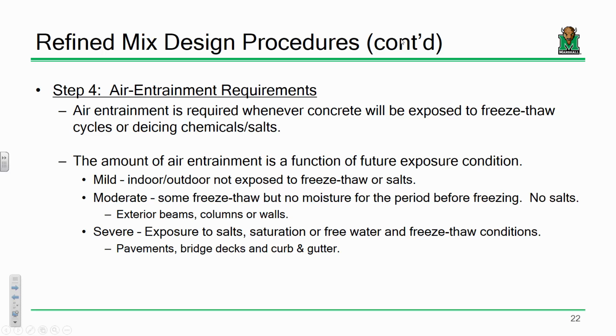Okay. So step 4, and like I said, we're just taking our ingredients one at a time. The next thing that we're going to determine is air entrainment. And that's one of the most important admixtures that we use in concrete applications. Remember, entrapped air is a bad thing. Entrained air is a good thing, especially when you've got concretes that are subjected to freeze-thaw cycles. A little bit of entrained air inside your mix is a good thing. It gives you a little bit of wiggle room during that expansion and contraction under freeze-thaw cycles.